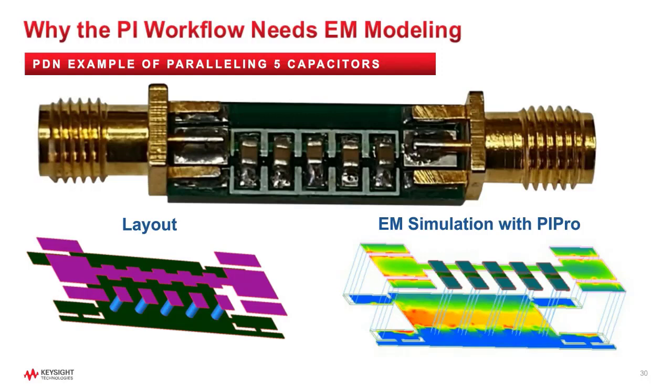The simple rule of thumb of selecting a capacitor using inductance divided by target Z squared is a good starting point to get in the right design space, but the actual selection of capacitors is not so simple. The C value you are looking for with the right C, ESR, and low inductance may not exist in a datasheet, and so it is typically necessary to parallel capacitors to get closer to the desired value. However, paralleling capacitors is a bit tricky. The physical location and the measurement points can result in some odd behavior.